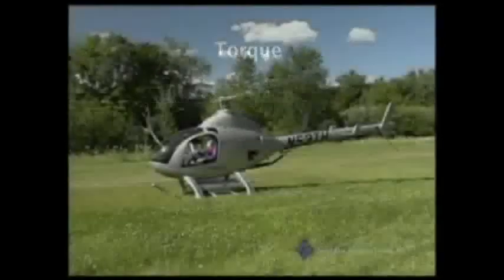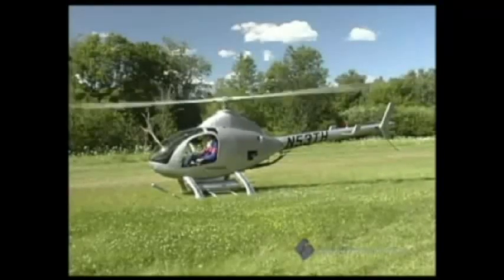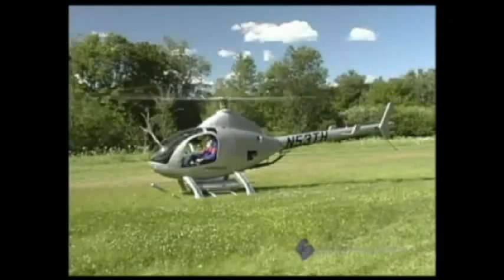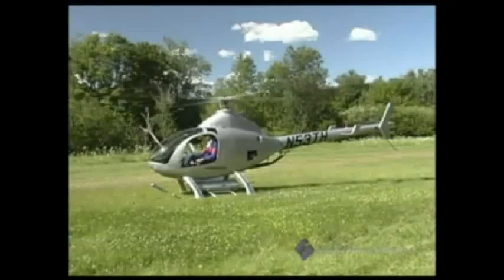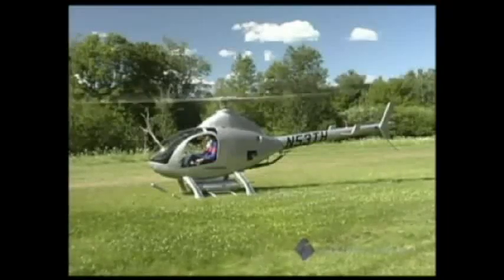According to Newton's 3rd law, the blades are trying to turn the helicopter in the opposite direction that they are turning. This is called torque. While on the ground, this problem is minimized because of the friction of the landing skids. So while on the ground, the body won't turn around the blades unless lots of power is quickly transferred to the rotor system, or the helicopter is on ice or floating on water.